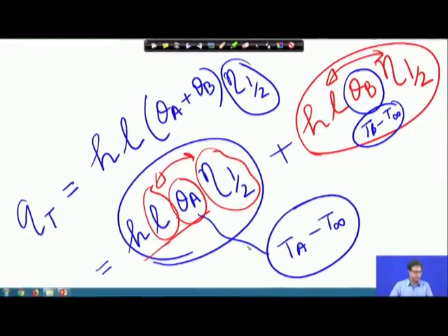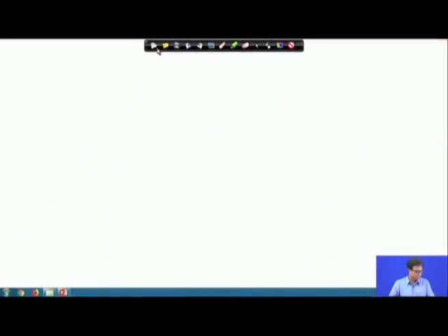So, as if we have half of the fin contributing to fluid A and the other half connected to the other fluid. This is basically the half fin idealization of the plate fin heat exchanger. This is a good assumption particularly for a 2-stream heat exchanger, but when we have multiple streams or a different asymmetric fin, we find a good deal of violation of this, and we then need to look into a different analysis. So, the total heat transfer is as if half of that fin is connected to surface T A, and the other half is connected to T B.